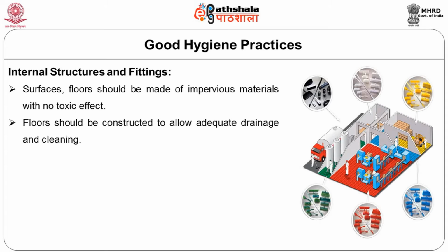And the ceilings and overhead fixtures should not allow buildup. They should be in such a way that they do not build up dirt or condensation or shedding of water. So nothing should fall from the ceiling that can become a contaminant in the foods.